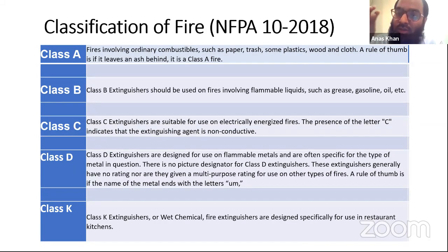So that's why in gas fire extinguishers, we don't have the gauge available. Otherwise, even if it is small quantity, it will always give you the full indication, and then you will be confused. So that's why we measure the CO2 fire extinguisher by means of weight rather than by means of pressure. Gross weight, to be exact. Weight of the cylinder plus weight of the gas.